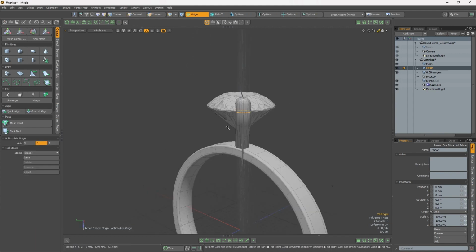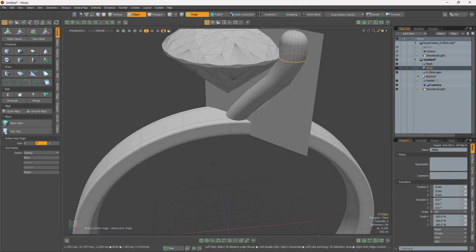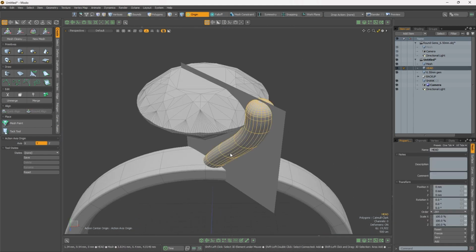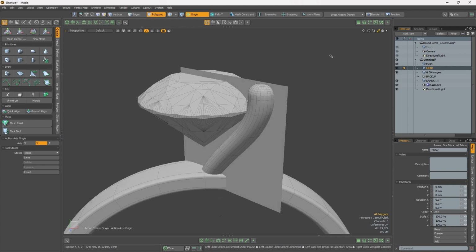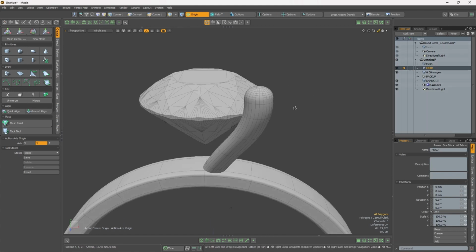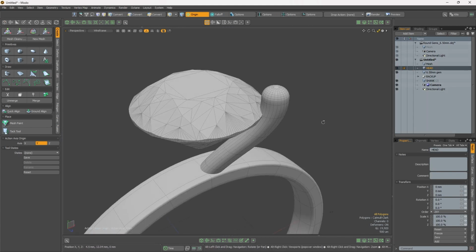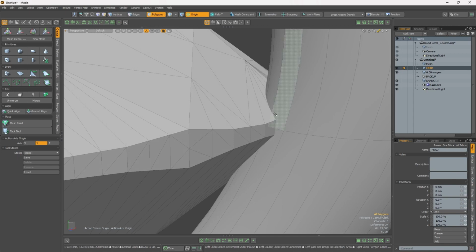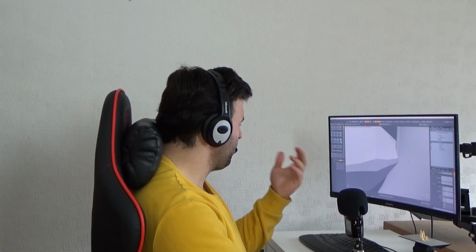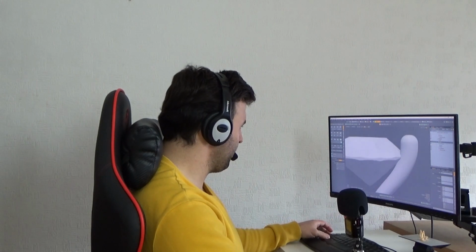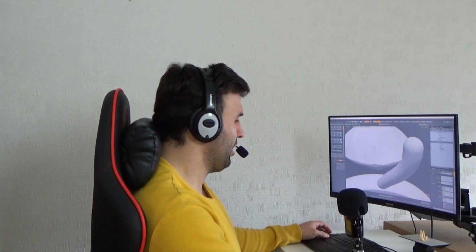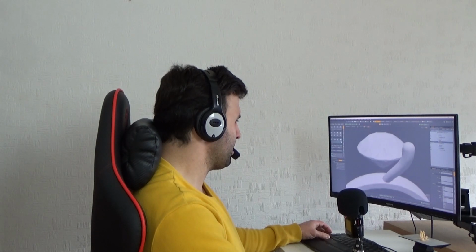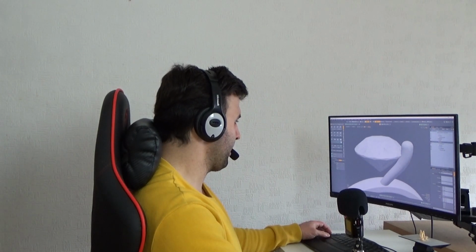Okay, so now I can, it looks better. The intersection of the claws, something about 0.2 millimeter, it's good enough. We don't want to have too tight an intersection, especially for a round gemstone. It's much easier for a stone setter to relocate the head if needed.